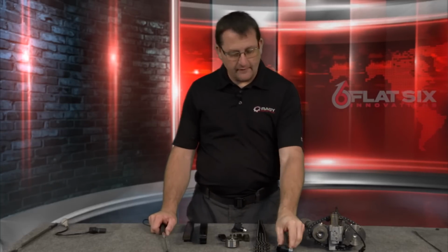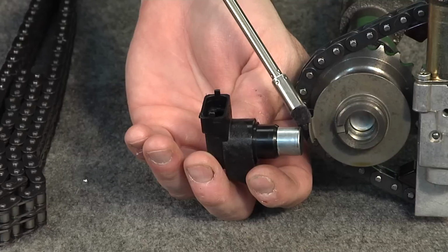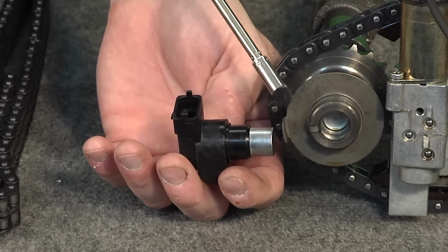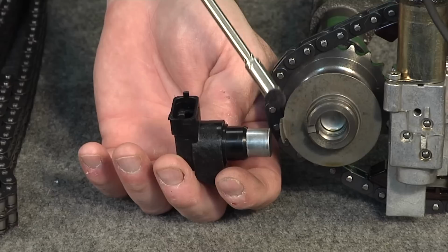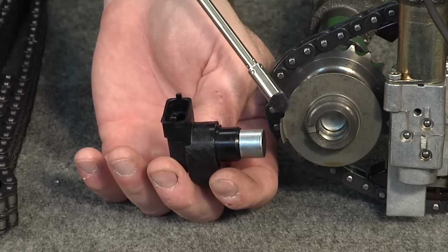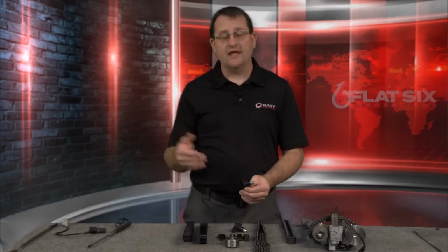So before we get started with all the other things about cam deviations, I just want to clear up a little bit more about these camshaft position sensors. This is one of the cam position sensors that I had a little earlier. It actually looks to this tang that's on the intake camshaft for the actual position of this camshaft. Now on the 3-chain engine it's a little bit different than that, but we're not even going over it because it's really not a concern, because 5-chain engines are the ones that have the biggest problems when it comes to chain cam deviations.